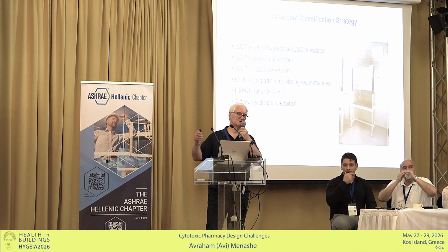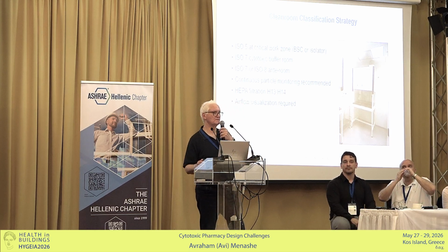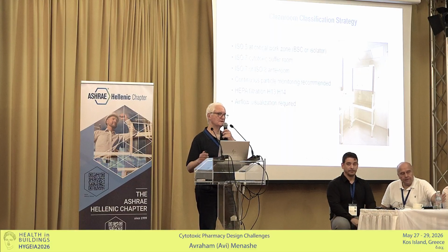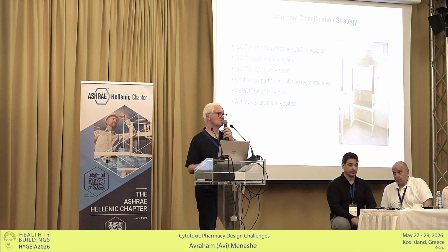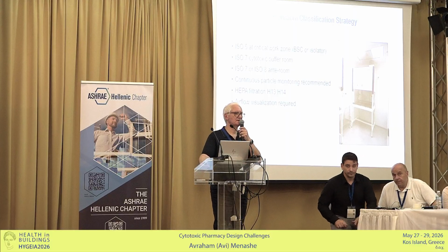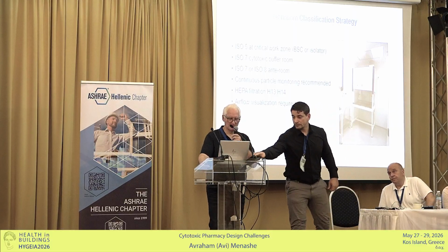Therefore, there are several tests during the year. There are special protocols where you have to bring in external companies that make all the measurements of the room. Of course, this is a clean room, so we are using HEPA filters, H13 or H14. It's 99.997%.